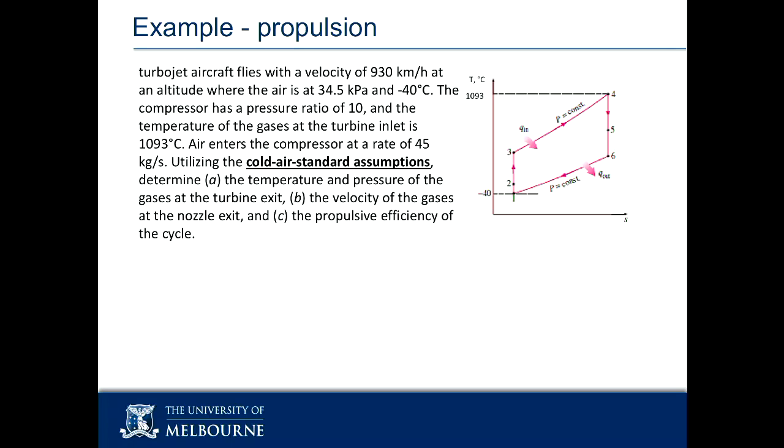So you're sitting there going kinetic energy, about velocity. You turn it into a number. You solve your enthalpy into a number and it's kilojoules. You try to convert kilojoules to joules without realizing you're off by 3 orders of magnitude and your number makes no sense. Or you don't notice that your number makes no sense and you write it down and you wonder why you got nothing, or a minus 1 or 2 marks. It's the most common thing to go wrong, so I'll try to do one.